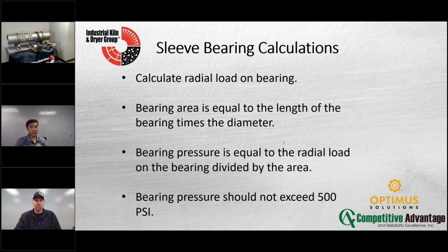In terms of the kilns, I haven't seen really in the market overall a vibration standard. And that's what's interesting to me, because now what I've learned is that the best way I can compare is a vibration from a like-to-like system. So if you have two units, then you're lucky because I can do a cross comparison. Right.